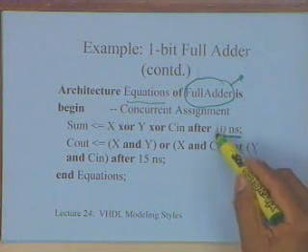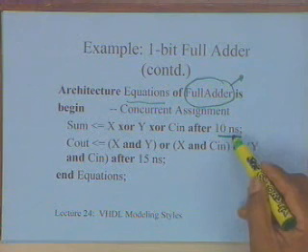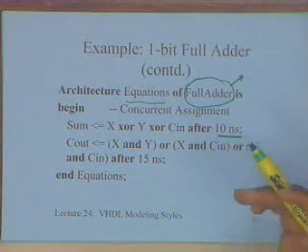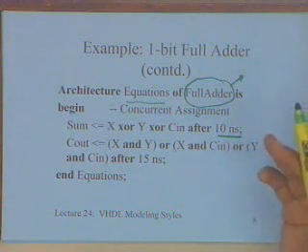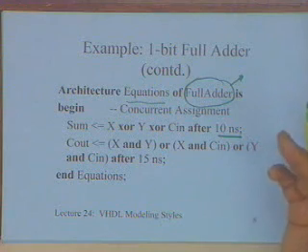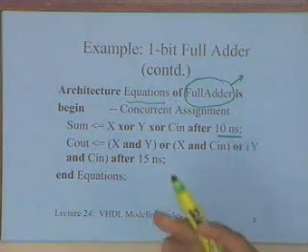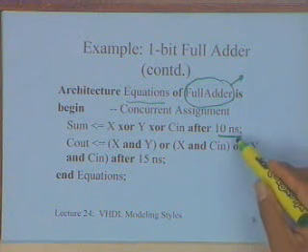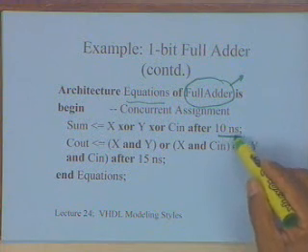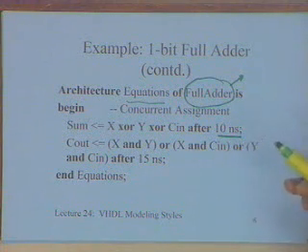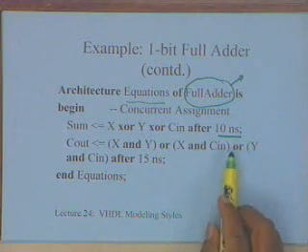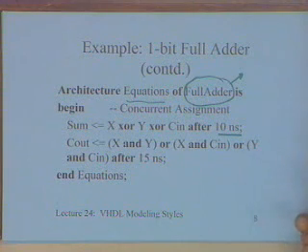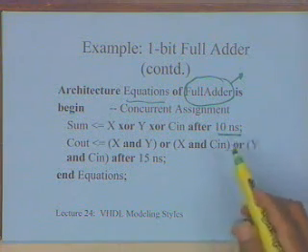Things like this 10 nanosecond timing are not really keywords, but they come as what are called standard packages. The timings are defined in terms of picoseconds, nanoseconds, microseconds using a standard package, which is available to you, like your type descriptions and so on. So the definition of nanoseconds will be defined over there. For all practical users of your VHDL, this will be available to you almost like a keyword, but they are not really keywords, they come through this.